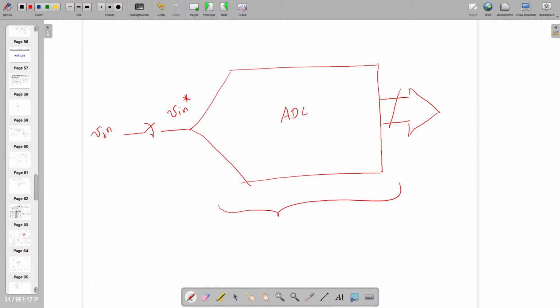Or if you can club this somewhere inside the ADC logic, then it's advantageous. But as you are studying at the beginning level, generally one sampling clock is needed on top of 2 raised to n number of T clock for the integrating type or dual slope ADC.